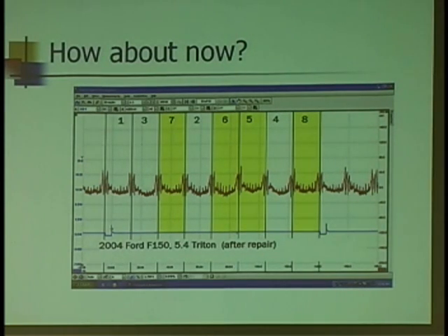Really nice, clean, uniform. The little spikes here, if you become more accustomed to scopes, you get what's called a little bit of noise, especially under hood. Under hood's a very noisy place electrically. Ignition's firing and injector's firing. Fluorescent overhead lights can cause noise in your pattern. The Pico's kind of cool because I can apply a filter to that pattern and take some of that hair out of it and clean it up, make it look a little cleaner. Okay? But knowing what it is, I'm not too concerned about it. What I'm looking at is nice and smooth.